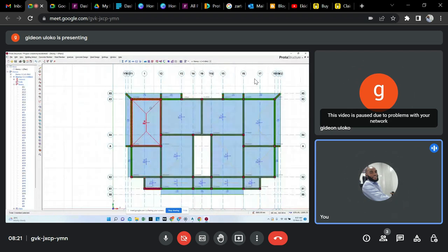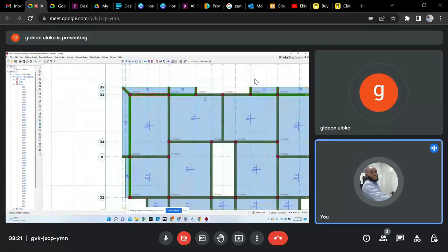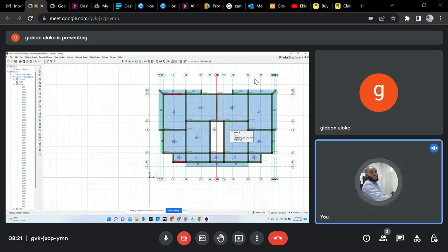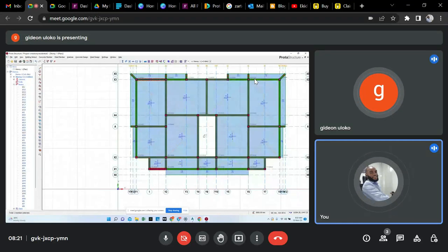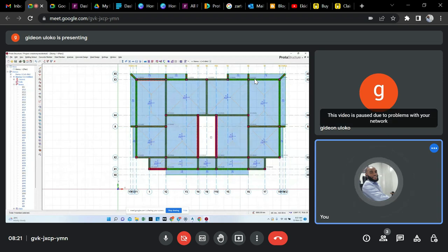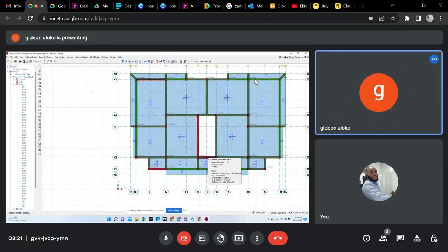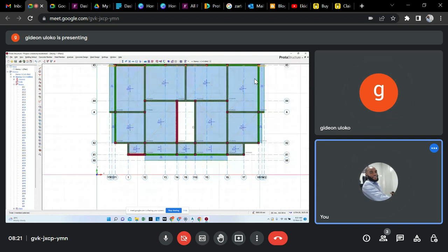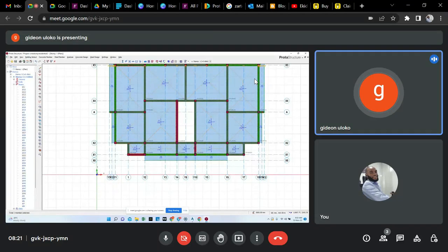That's not an I. That vertical one is a J. So vertical ones also at the bottom, we also hinge. These ones near the staircase will be hinged at both I and J. So first of all, hinge the I end first. No, not that one. The next beam below it. Sorry, the vertical one at the staircase below it. Yes, this one.